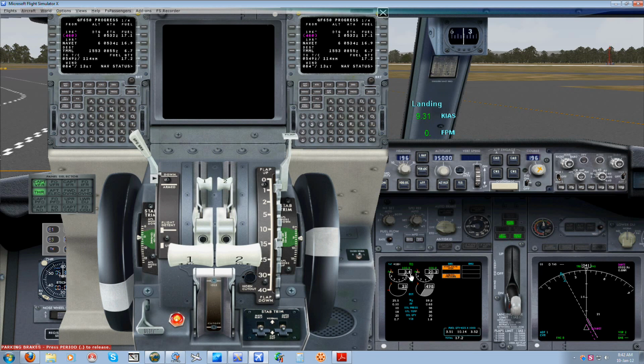You'll see engine 1 N1 coming up, the exhaust gas temperature coming up, the fuel flow, the oil pressure, oil temp, oil quantity. Well, that won't change, but the vibration. So things you're looking for on here is you're mainly watching the oil pressure and the oil temp. So if your oil pressure drops or your oil temp rockets, then you need to shut down the engine immediately. So that's all good, no problems there. That's a textbook engine startup.